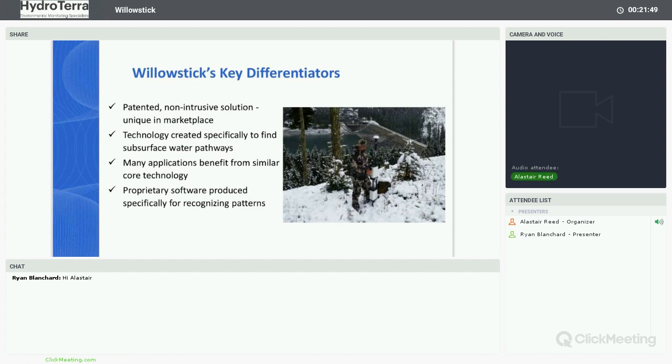A lot of cost can be incurred installing many wells, trying to identify flow paths or leaks in dams, etc. This type of technology is able to characterise large areas quite quickly and produce models that can help with decision making on how to remediate, whether it be utilising cut-off walls or grout curtains.